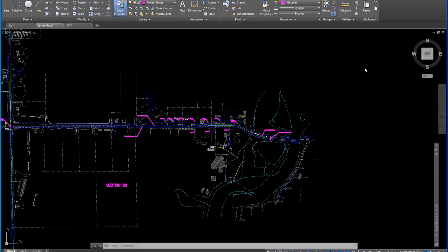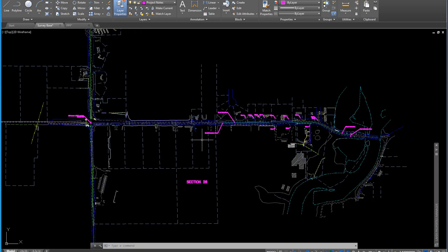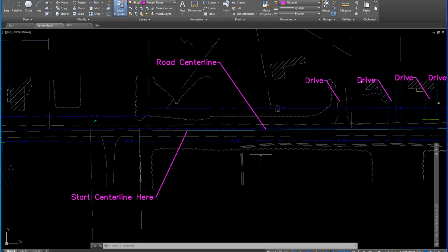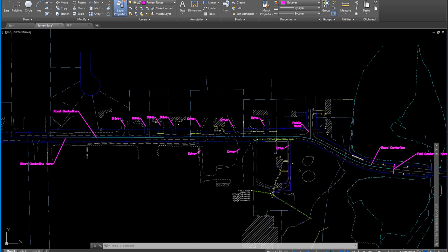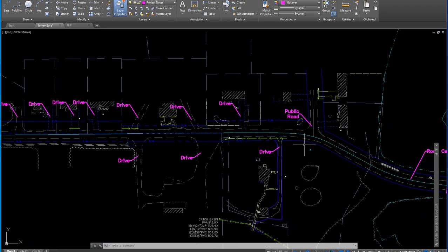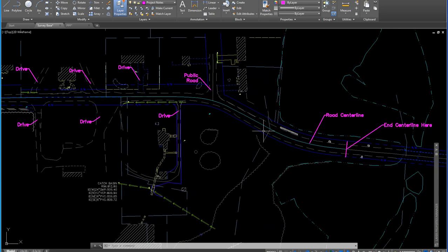Also wanted to show you here in AutoCAD what the drawing looks like when you open it up. Over here is the section corner in the center of this intersection. That's where they almost always are. It's section 28, I'll label that for you. Then you have to draw over the top of the center line and make a polyline out of what you drew in. And look, there's a couple of curves in there. You get to practice that.